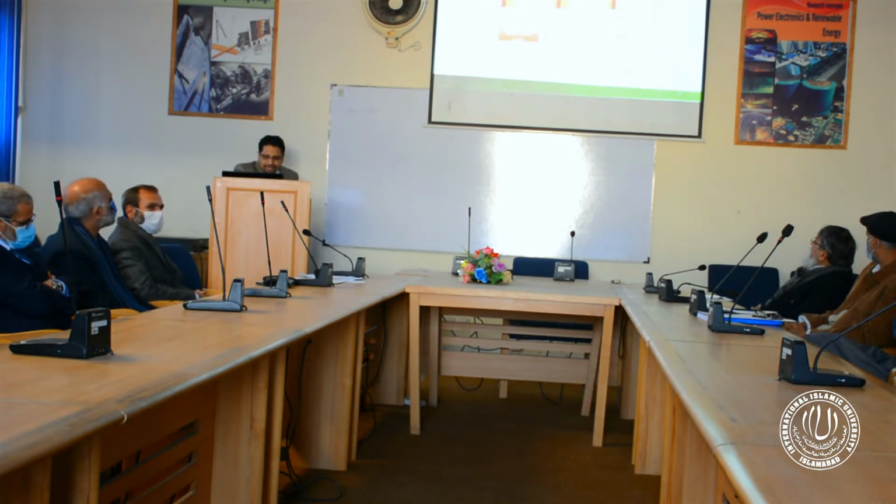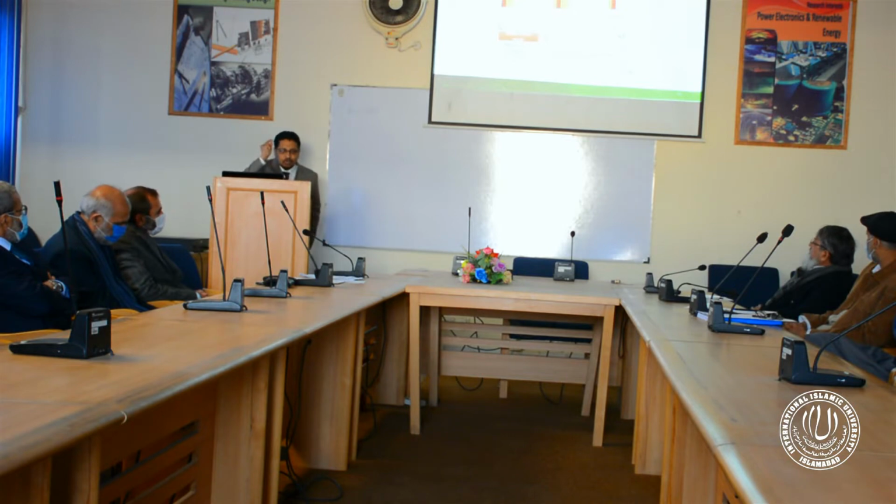This red line here, rectangular, represents the time energy taken for the radar to transmit, which is the pulse width of the signal. And after that, the radar goes into silent mode during the PRI, the pulse repetition interval time. So the total time is Tw plus tau R. Tau R here represents the rest mode.